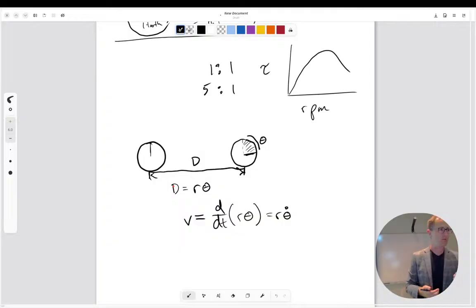If we know the radius and we know the gear ratio, we could say for this given speed, and maybe we want to choose the gear ratio: I want to go this fast, and I want to pedal at this speed. What gear ratio do I need? That's a solid sort of question, and it goes both ways. Whether you have an engine, like I want my engine to do 3,200 RPM, or I have a body that wants to do 2 hertz.